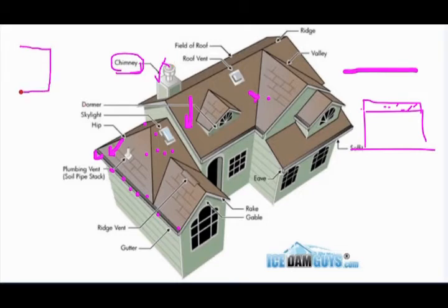So in your plan, you have some ducts. Am I right? So these ducts, I need to see all of them in the roof. All of them will come like that, at least 50 centimeters up to the roof. We need to see them. This is another critical problem that we have to know, and we have to somehow respect. And look at here, at least 30 centimeters, depending on the project, maybe 1 meter should work, should have distance between opening of the dormer,